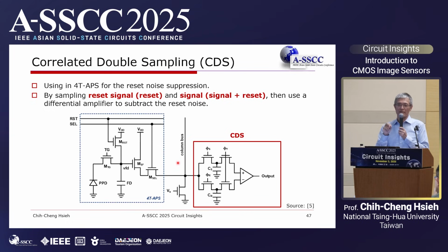But the drawback of DVS is that it is nothing like the conventional image sensor, so you need to define a new interface, including the data format. So the existing signal processing system cannot deal with the output of DVS directly. You need some transformation to utilize the existing signal processing engine. So that will be a big problem so far.